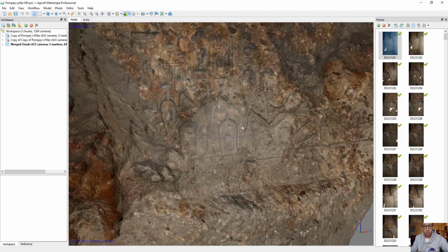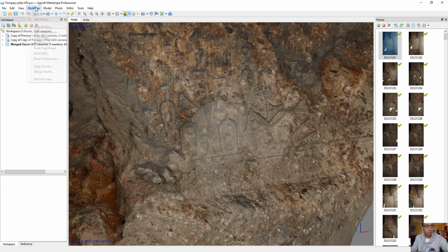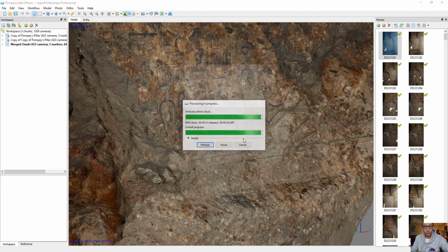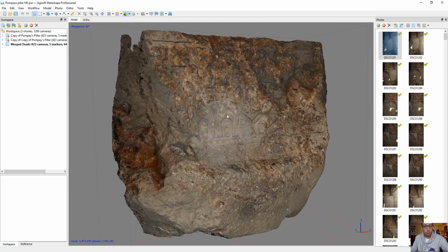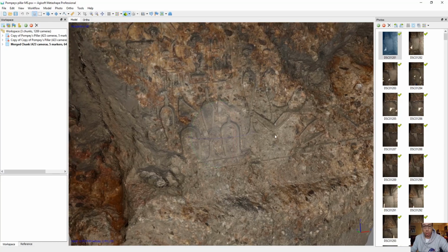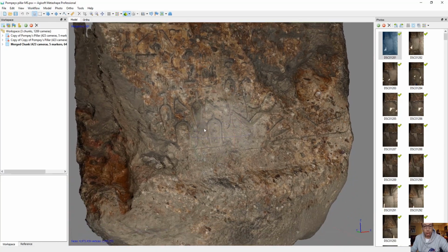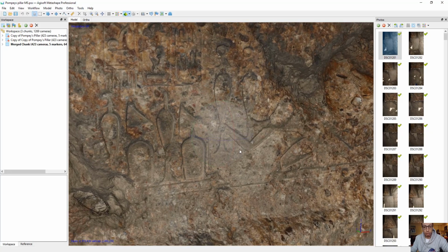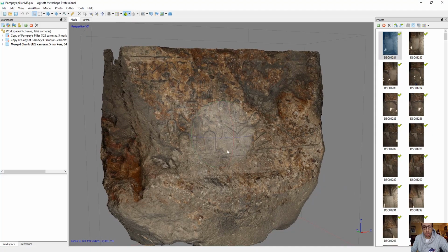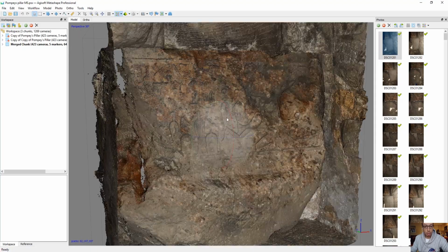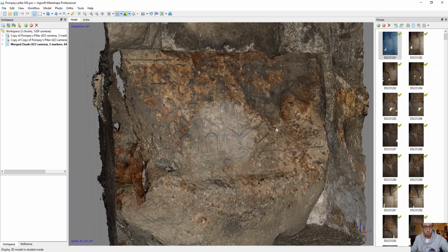Most people who buy the new version of Metashape don't use the dense point cloud anymore. You just go to build mesh, creating the surface based on the depth maps, choose high or ultra high and press OK. This method is extremely fast and much more reliable than using the dense point cloud, but some people still prefer the dense point cloud for extra editing of the points. It's much easier and lighter to control than a high resolution mesh.